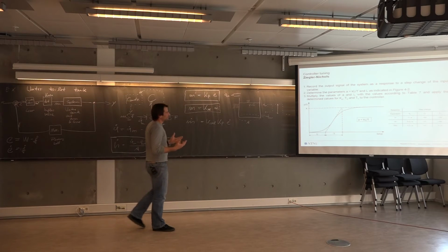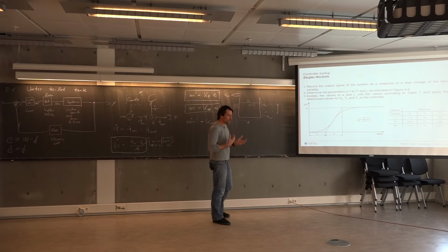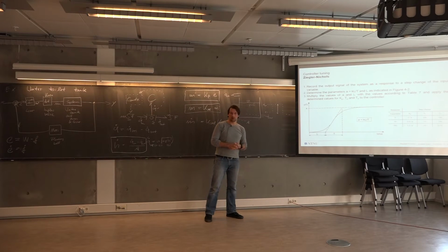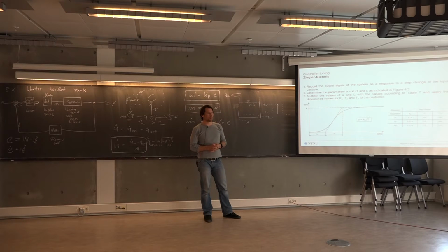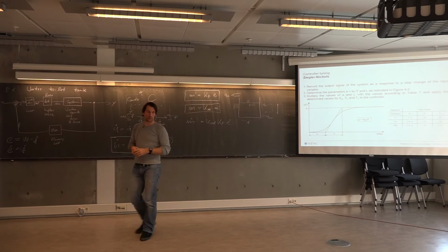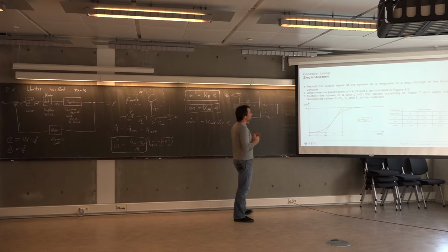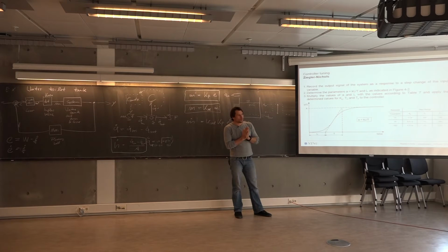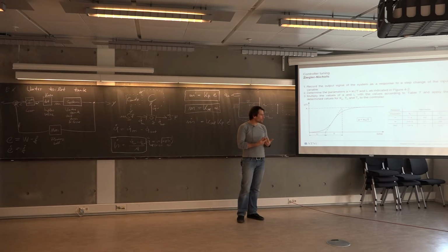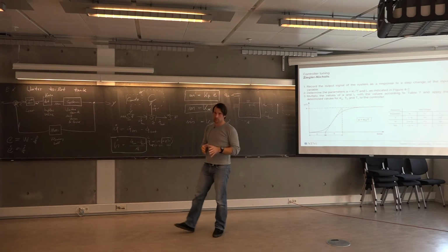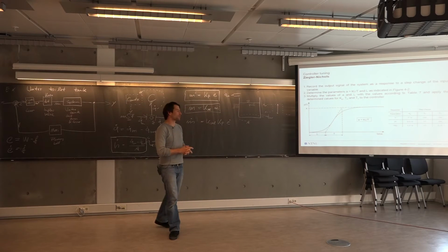I guess the most straightforward method to tune this PID controller, or any of the previously mentioned controller types, PI, PD controller, is to make use of the concept of Ziegler-Nichols, two guys who came up with this. And it's basically fairly straightforward. First of all, you record the system response that you get when you impose a step change on the system.